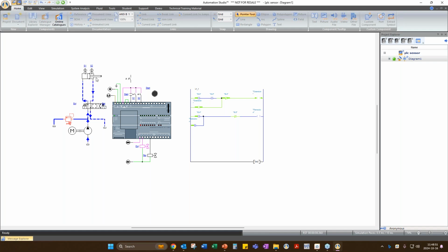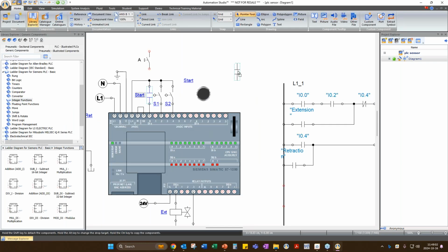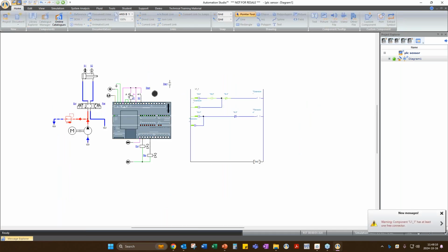So it will get extended. S2 is getting sensed. Okay, it will actuate and it will get back to the position. So I can automate that also. If I remove this and put in this push button, if I want to operate it for a number of times, it will perform those operations until I make it off. Okay, can you see these are the sensors, position sensors. By using the ladder diagram, it is going to perform the operations, extension, retraction, all these things.